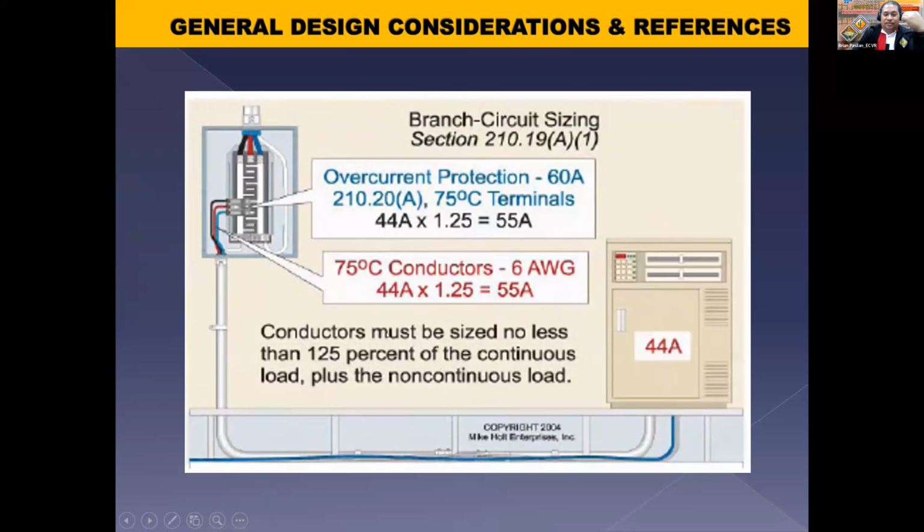Okay. So meaning to say, as long as your load is a single load only, not part of a multiple outlet. This is one of the conditions where we are permitted to allow the next higher standard rating, as long as it's up to 800 amperes, no? These are the only conditions, okay? So these are examples where we are allowed, as long as it's only one load. Okay? The wisdom behind that is this, no?